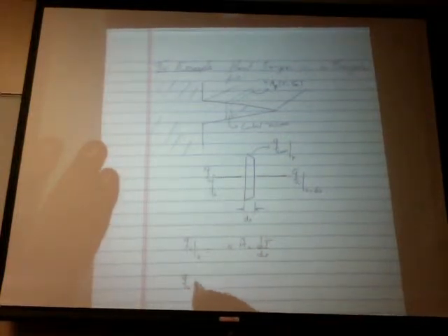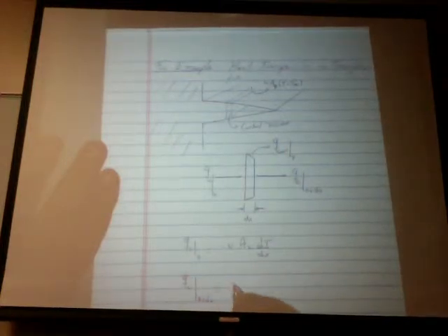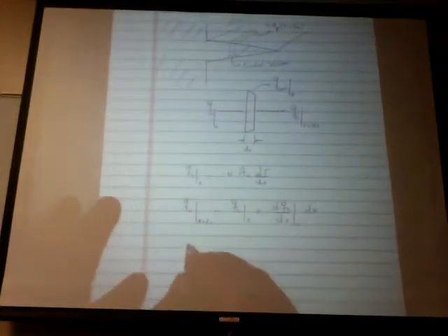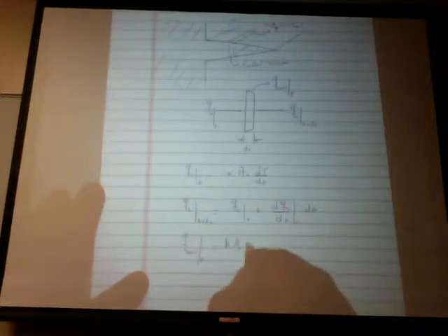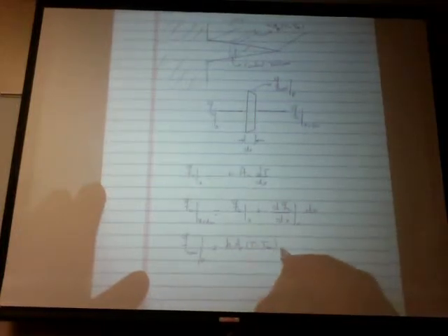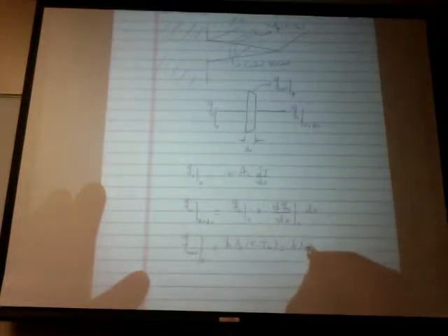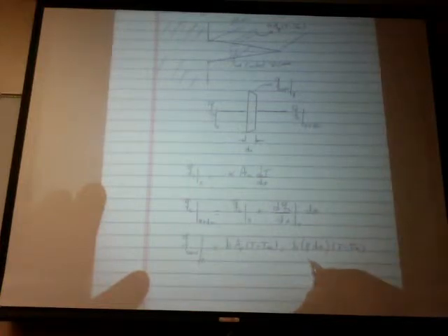Well, the conductive heat flux that comes out at x plus dx would be QC at x plus dQC dx at x times dx. This is a Taylor series expansion. And Q convection at the periphery is equal to H, area of the periphery, which is equal to H P dx, where P is the perimeter, times T minus T infinity.